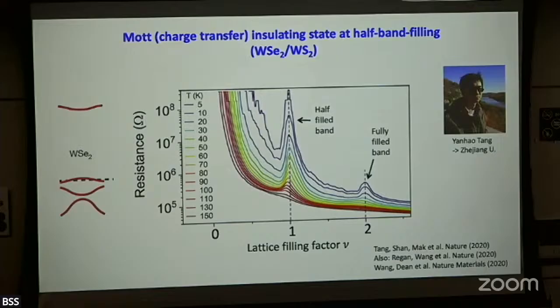Let me digress and say a few words. The current design is that we make the sample into two different regions. One has a low doping density, which you can control, but the part where you put the metal gates, you heavily dope. That way you can achieve a good metal-to-semiconductor contact, and from the heavily doped to the lightly doped part you have a relatively small barrier.